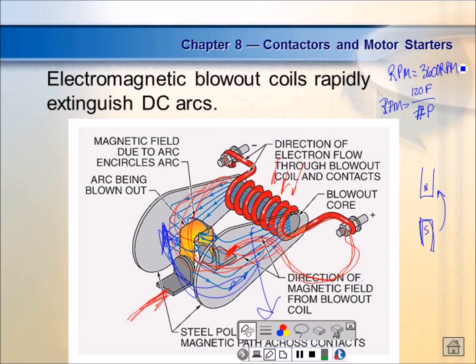You got a little switch, click, click, click, and if you took that thing apart, you'd see the switch has 3 wires coming out of it. And every time you click it, what are you doing on your ceiling fan? You're changing the number of poles. Okay, you understand that? Does that make sense now?